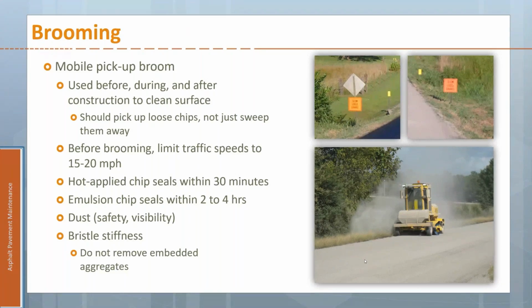So put up signs, talk to the neighbors, the folks in the area, let them know what you're doing, try to explain this. But this is when you're most likely to have rocks in the windshield, because there are still going to be some extra chips that are there. There will be some shedding. We need to get that cleaned up, but we can't get on it too soon or we'll start peeling some of the aggregates out of that binder. We need to let it set. We need to let it cure a little bit.